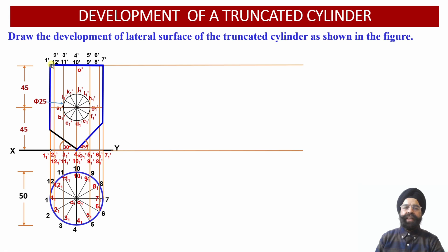line development method. So from the two extreme ends of the cylinder, that is from the base of the cylinder and from the top face of the cylinder, we have drawn two projector lines over here, and onto these two projector lines, which are horizontal projector lines, now we are going to mark distances corresponding to these 12 sectors of the circumference of this particular cylinder over here. So the distance between two consecutive points over here we are going to mark,